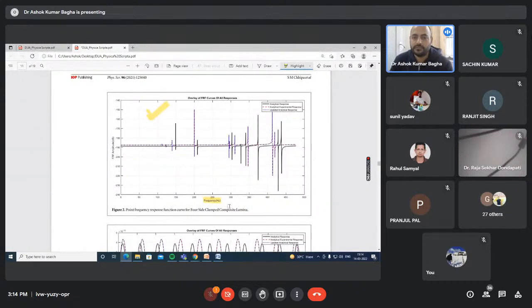On the x-axis there is frequency. On the y-axis there is the FRF in dB, decibel. And this morning he told you why you plot in dB: because if you do not plot in dB, the importance of the vibration modes whose value is small will not be shown on a linear scale. You will see there are different frequencies here. This is the first fundamental frequency, the second fundamental frequency. According to the peaks, you can find out the natural frequencies of the system, right?